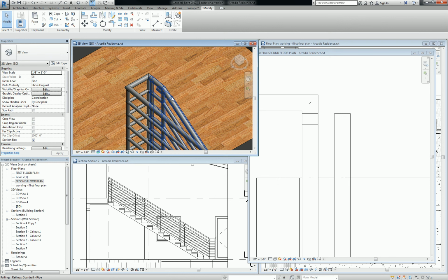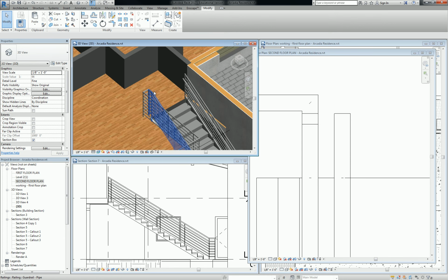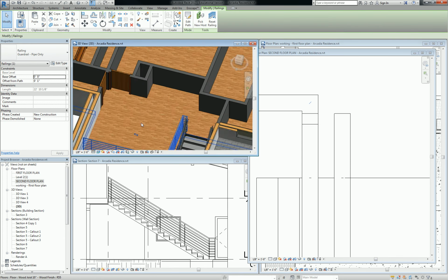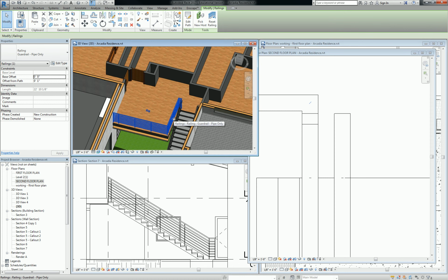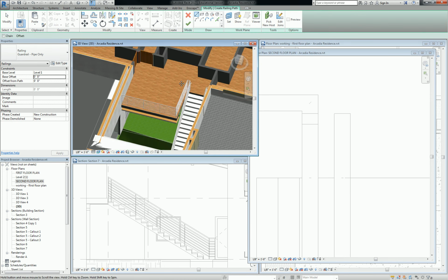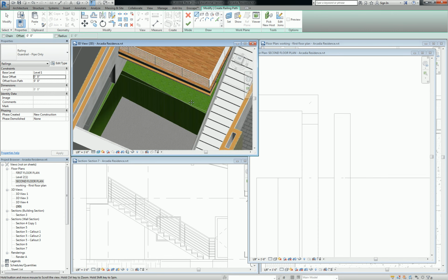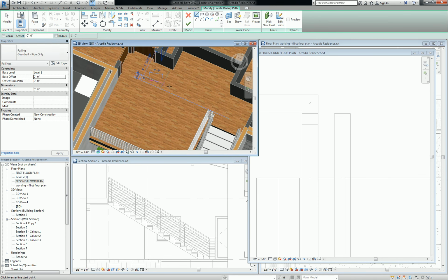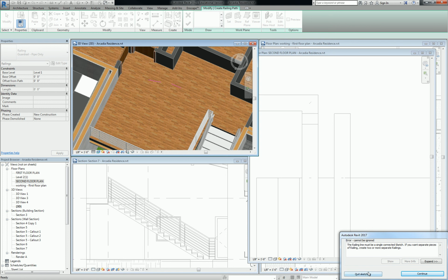What do you mean by load? I mean, like when you finish drawing your stair path. Yeah. So if, let's say you draw 2 line segments and they're not connected, it won't let you okay that? I don't think so. It's actually been a while since I've tried that, but I think if you try to draw 2 separate line segments, it won't let you. Yeah, the railing line needs to be a single one.